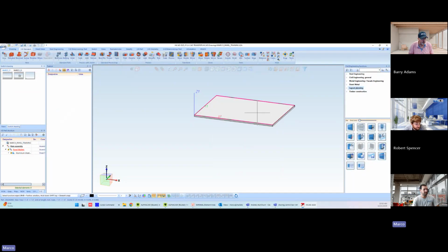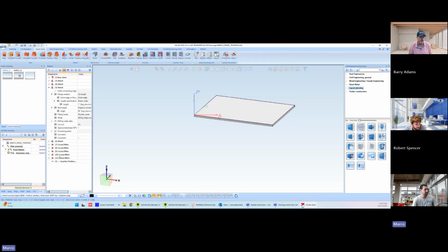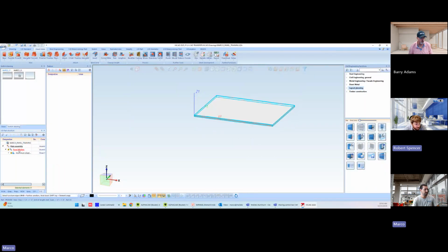So you want to save this panel assembly, which is going to be the middle one in your structure, because think about it for a moment. Right now we only have a sheet metal piece in there, but in a complete panel, you're going to have stiffeners and clips and brackets and whatever else in there. So you want to resave that whole variant assembly, not just the sheet metal part.